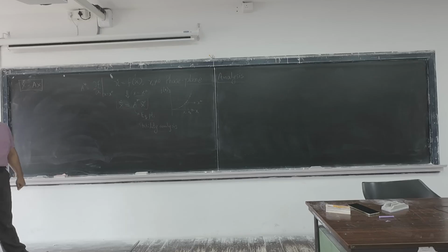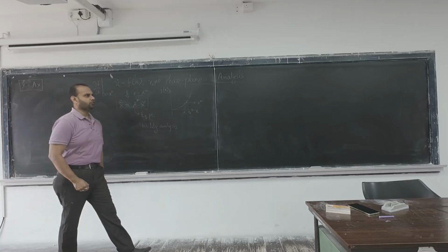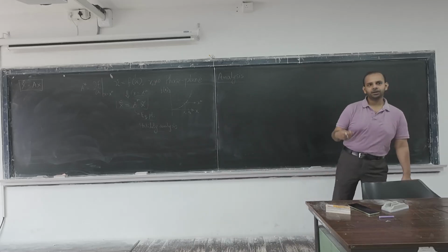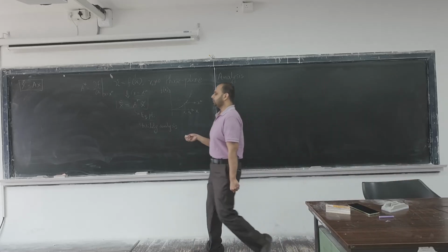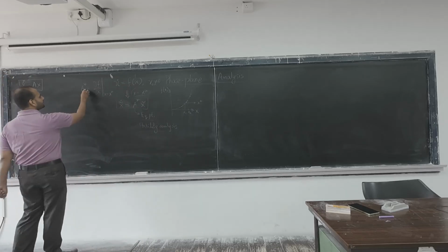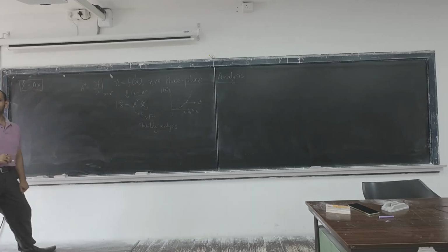So that is the concept of Jacobian linearization, right? Which at the core is this Taylor series expansion. Last week I showed a little bit, although we haven't yet formally learned Taylor series. Depending upon that, you could remember that I only wrote that expansion, right? So from that, there is A star equal to del f del x at x equals x star.